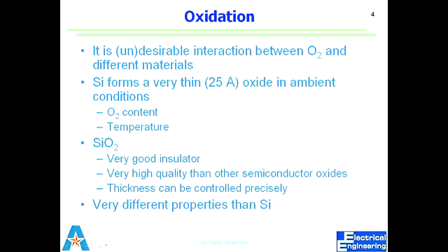What do you think? Native oxide is good or bad? Depends on what you're doing. If I leave my wafers for a longer period of time, can I live with native oxide? Remember, many times this oxide or nitride layer, we use as the final material that covers everything, and we call it the passivation layer. It buries everything, so everything is buried below. There's no more chemical change that can occur because now we have this protection layer on top.